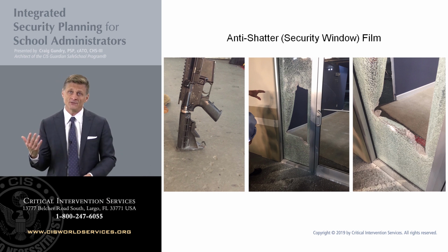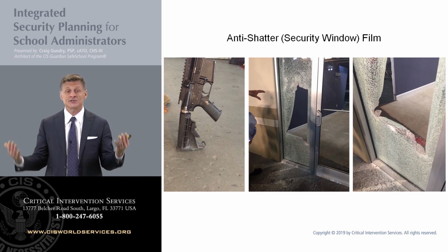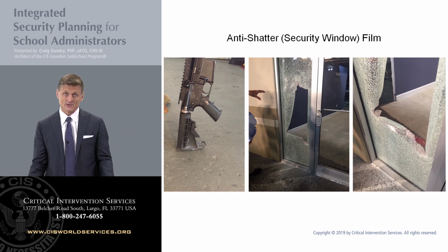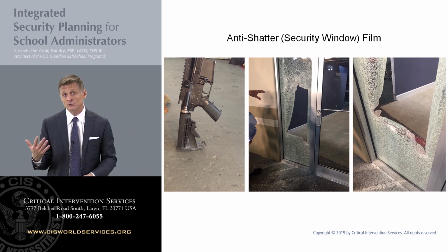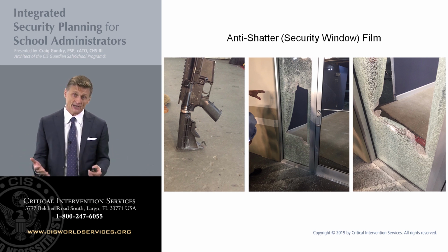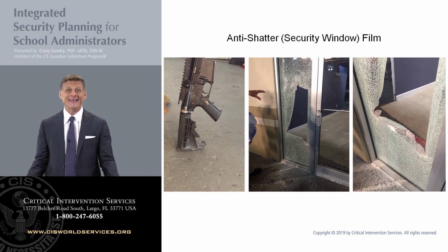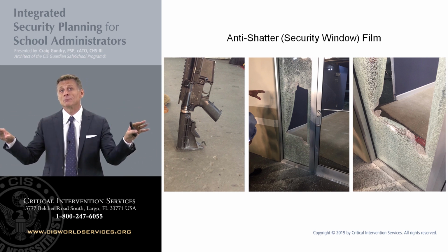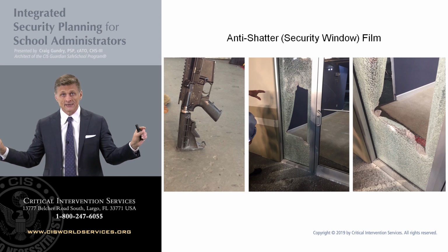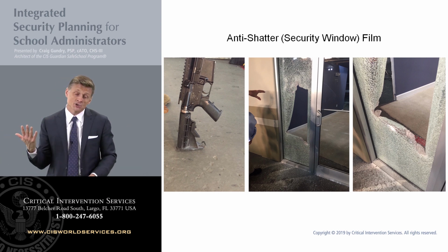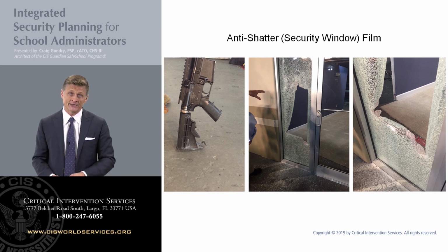Also, if you have, let's say, exterior glass doors with relatively thin frames, you will not be able to utilize window film. Although I don't encounter this often in schools, with my commercial clients, office buildings, I do encounter occasionally main entrance doors that are basically solid panels of glass at the top with no frame at all. In that case, you will not be able to use window film also. It would require actual replacement, probably with something like laminated glass.